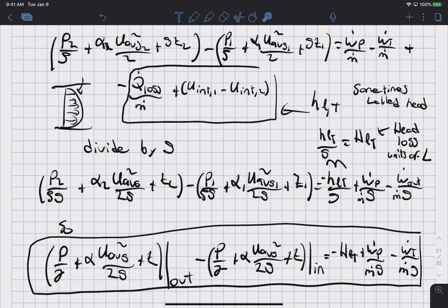And so what these viscous losses do is they cause a combination of heat loss to the pipe or a slight change in the temperature. If you remember the example I did in class where we had that water flowing downhill from a very long reservoir, all those losses, and it was 20-30 horsepower, amounted to a 0.01 degree change in temperature.